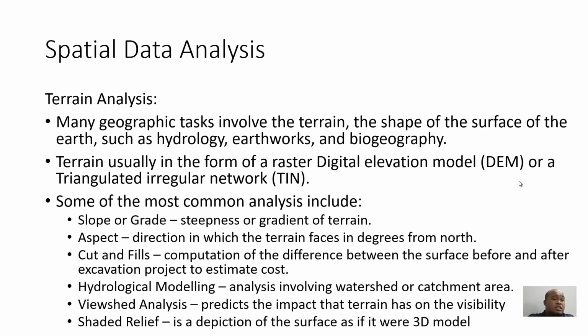The viewshed analysis predicts the impact that terrain has on the visibility, right? The viewshed can be understood as, if you are standing on one point and you are looking at a view, right? Let's say a new landfill site is constructed in your area. So whether from your house you can directly see the landfill site or not. That analysis can be done by using the viewshed analysis.